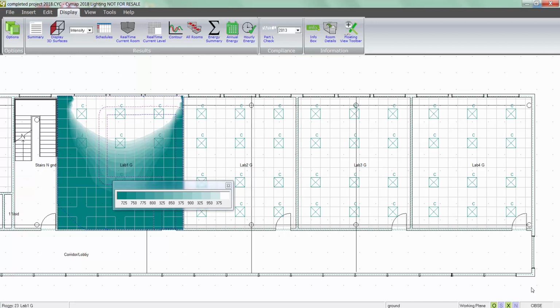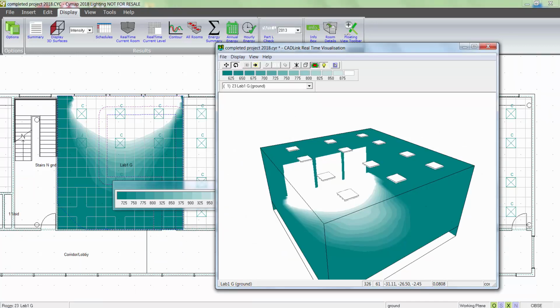The lighting program enables the engineer to automatically lay out light fittings based on lumen methodologies. This then places the fittings within space automatically, optimises them to either conform to a ceiling grid arrangement or independent of the ceiling grid. 3D views can also be applied for visualization purposes.